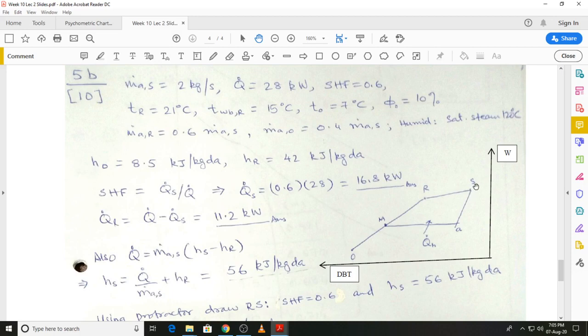And remember that in the basic heating cycle, the supply state will have a higher humidity ratio and a higher dry bulb temperature than the humidity ratio and dry bulb temperature that are required in the conditioned space, and that is to balance the heat loss, and that heat loss will have or can have both sensible and latent components.